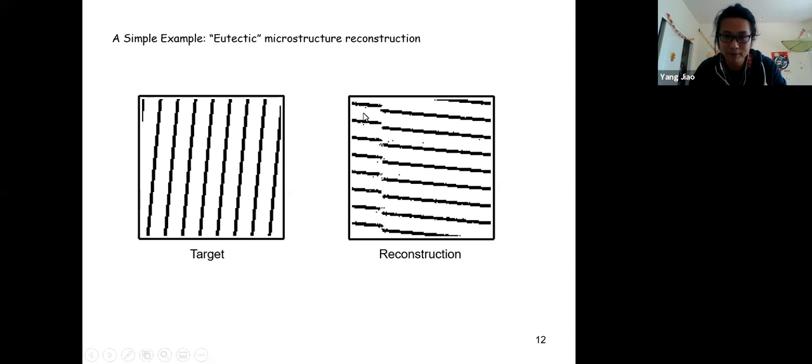But if you think about that, this is another degeneracy we have. When we use reconstruction to make sure that each part of the system is treated equally, we use periodic boundary condition. Although in the reconstruction we explicitly focus on this small domain, we're imagining that you have a repeating tessellation of the whole space, or whole 2D plane, using this pattern. So if you're looking at a corner here, the corner is going to go back here. So we use a periodic boundary condition.